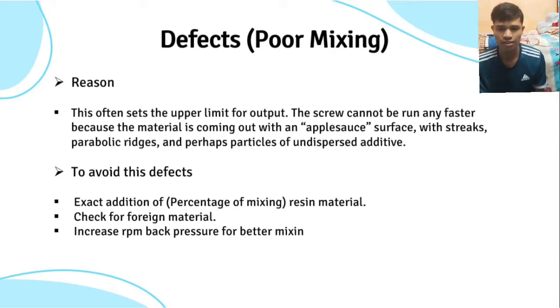To avoid the defects, add exact percentages of mixing resin materials, then check for foreign materials, and lastly increase RPM and back pressure for better mixing. That's all for me. Thank you.